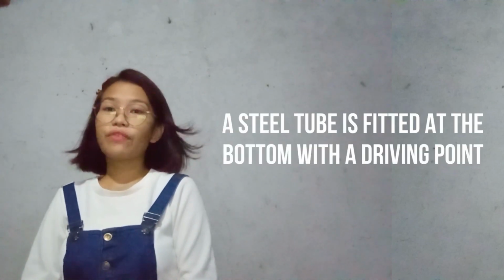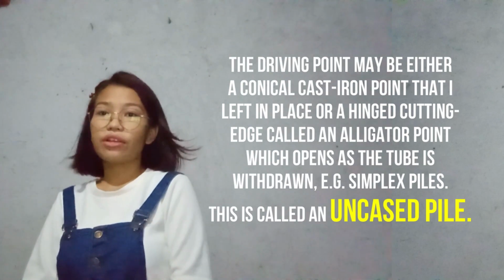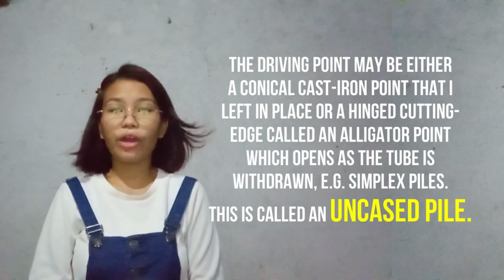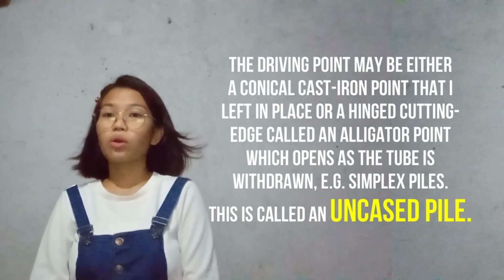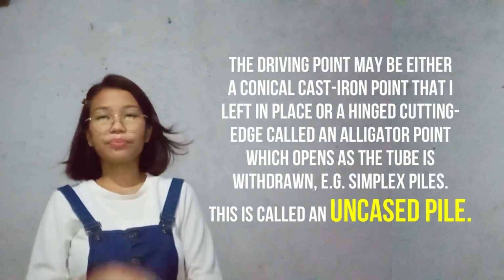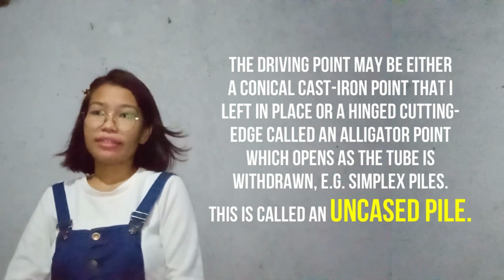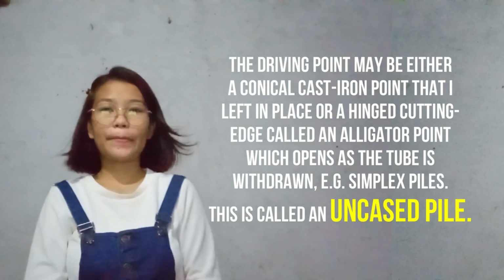A steel tube is fitted at the bottom with a driving point. The driving point may be either a conical cast iron point that is left in place or a hinged cutting edge, called an alligator point, which opens as the tube is withdrawn. Simplex piles. These are called uncased piles.